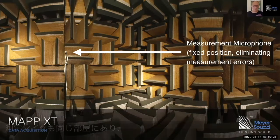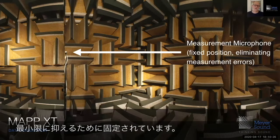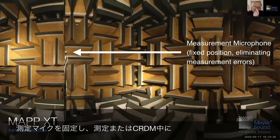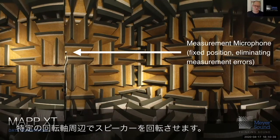Our measurement microphone obviously also lives in that same anechoic room, and it's stationary to eliminate measurement errors. So we're not orbiting the loudspeaker with the measurement microphone. The measurement microphone is stationary, and we're rotating the loudspeaker around a certain center of rotation during measurement, or CRDM.